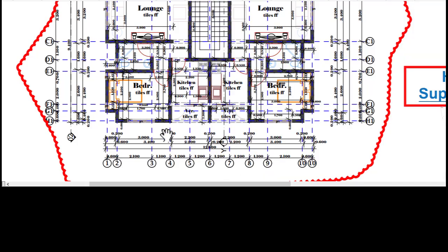Yes, so the part between grid 2 to grid 5 is identical to the one that is from grid 7 to grid 10. Alright, so that is also taken into consideration, and that actually gives us the last part of the internal wall that we needed to take care of. So we just do away with that plus and have the equal sign. So that gives us a total length for the internal walls of 40.9. Okay, so 40.9 is now the total internal wall length.